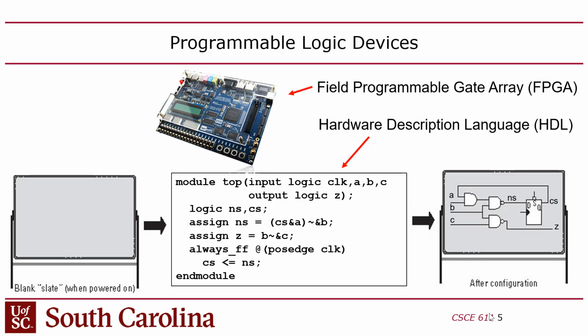Like you can have an I/O pin that can be 3 volts or 2.5 volts, or it can be LVDS, low voltage differential signaling, where you use a pair of pins to alternate their relative voltage. So they have all these things in there. And it's all programmable, right? In fact, that's kind of the company motto of Xilinx, all programmable.